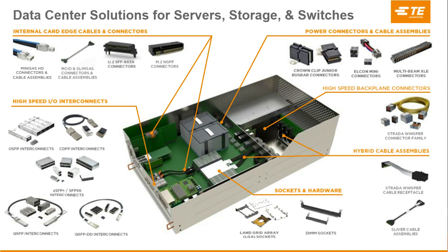Another growing trend is in DC power distribution. Large scale data centers are moving to 48 volts for the DC power distribution inside the building. That reduces I²R losses by a factor of 16, and TE's busbar products are a key enabler to realize those efficiency improvements.